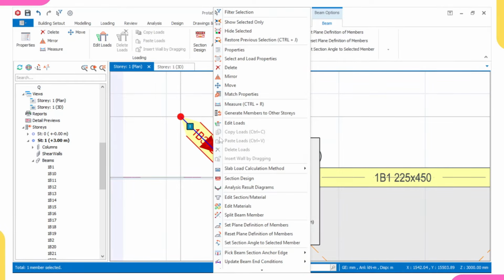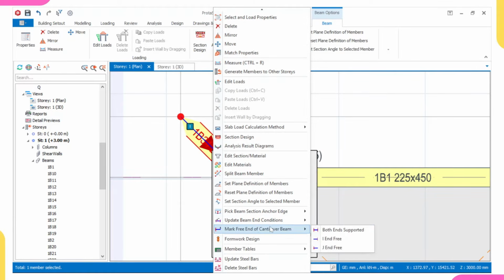Then I'll remove this cantilever sign, because remember I told you that I could have rested the column on top of the slab, but due to the fact that ProtaStructure sees it as an error, that's why I inputted that hidden beam. So I'll click on this, say okay, and just leave it.